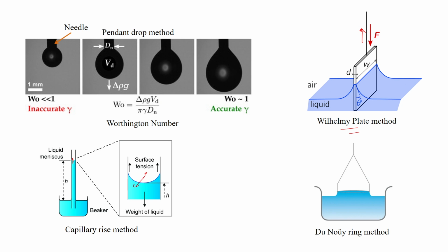We know how to relate the pressure difference across this interface to the surface tension, which is called the Laplace pressure, and then we can relate it to the height, the hydrostatic pressure over here, and that will give us an estimate of the surface tension. But you have to make sure that we measure the contact angle correctly, or that we use a capillary within which the liquid wets completely.